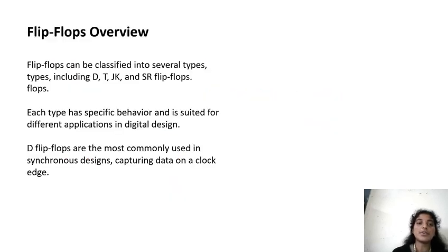Flip-flops overview. Flip-flops can be classified into several types including D, T, JK and SR flip-flops. Each type has specific behavior and is suited for different applications in digital design. D flip-flops are the most commonly used in synchronous designs, capturing data on a clock edge.